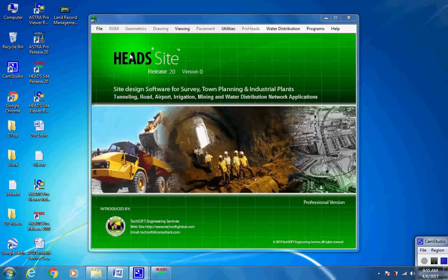The estimation of earthwork in cut and fill is computed accurately by software HDS Site in well-formatted tabular format following stations defined along the reference line. Along with the digital terrain model, DTM, it generates contours, elevations on grids, 3D surface etc. and all as CAD drawings. The built-in CAD engine is highly powerful with complete drafting and editing facilities. The drawings are compatible to AutoCAD and all other popular CAD softwares.